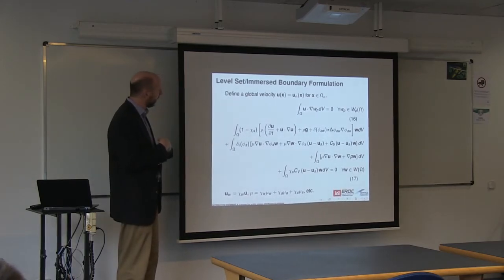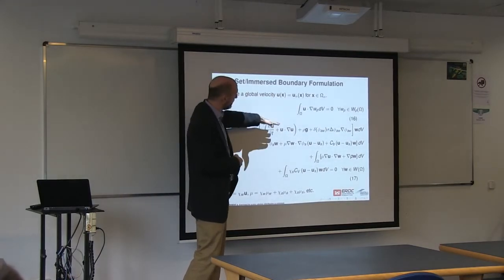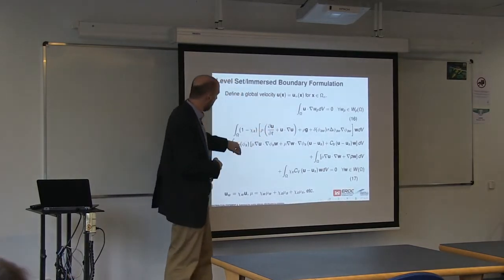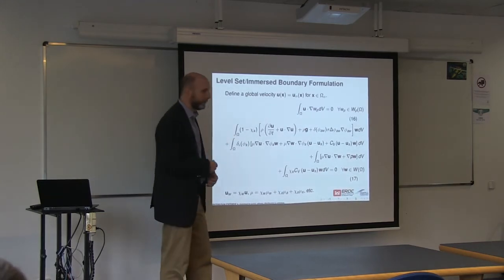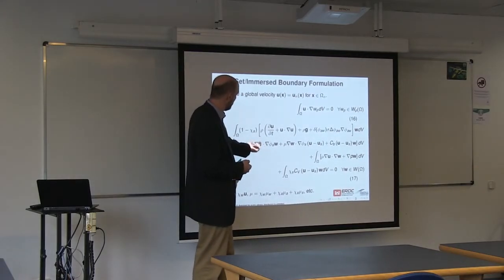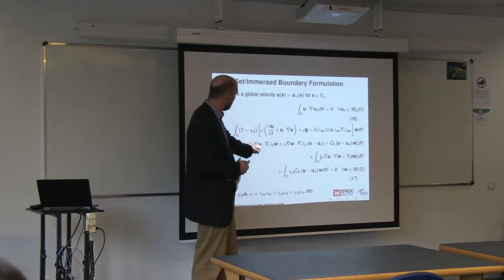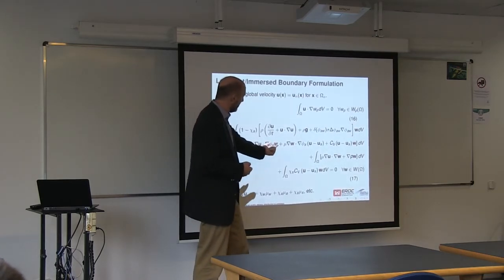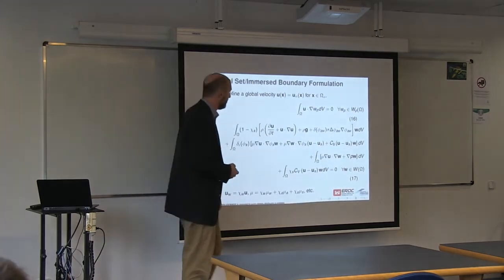And the way that we've been doing that, for the most part, is we take our Navier-Stokes equations, which gives us continuity and a momentum balance, and then we do a boundary integral for our solid surface grains where we represent the no-slip condition, but we enforce that boundary condition using the Nitsche method. So we have, instead of just a simple boundary integral, terms that look like the flux term and the momentum that would arise by integrating the stress by parts, and then we have what's called an adjoint consistency term, and a penalty term that arise from the Nitsche method.